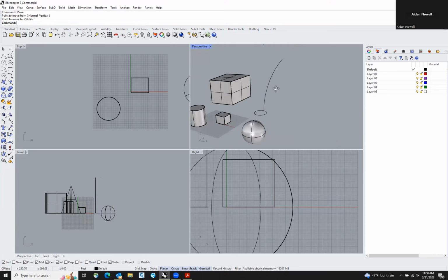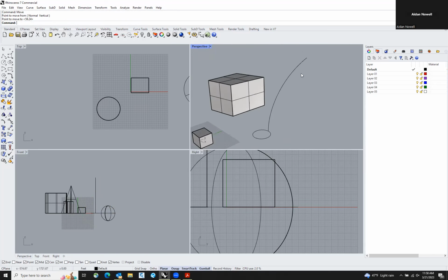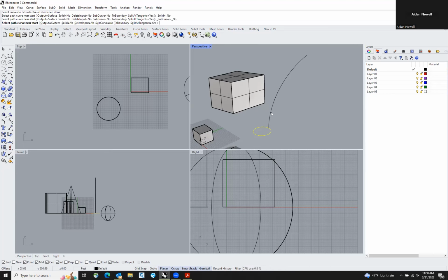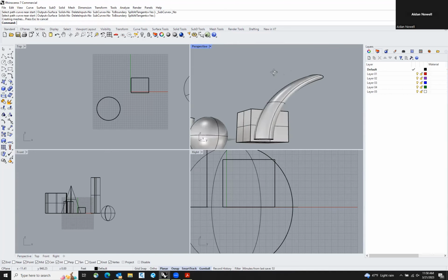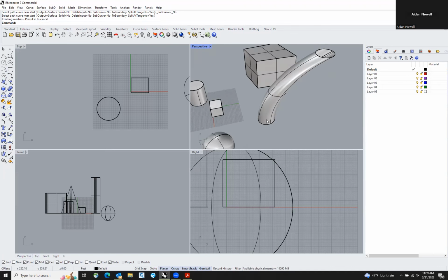So now you have this kind of like the Little Dipper type of thing going on with a handle and a circle. You can do this cool thing called extrude along curve. So I'm going to click that point, select curve to extrude, press enter, select path curve near start. So I'm going to select that near the start. As you can see, it took that curve and then extruded it along that other curve.